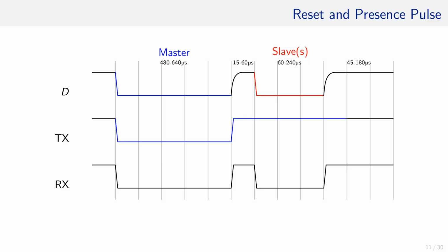Then, in one wire, we have the presence and the reset pulse. However, the reset pulse is a lot longer than 60 microseconds that we have the UART frame configured to be in. If the UART is to mimic that reset pulse, including accommodate the presence pulse, the TX line has to stay low for at least 480 microseconds initially. After that, the wire can recharge, hence we write a 1 to the bus from here onward.